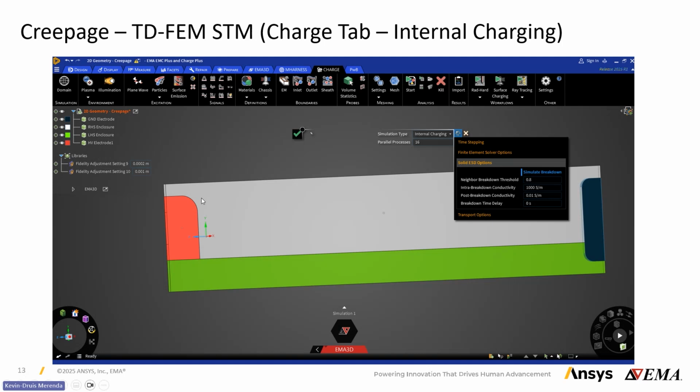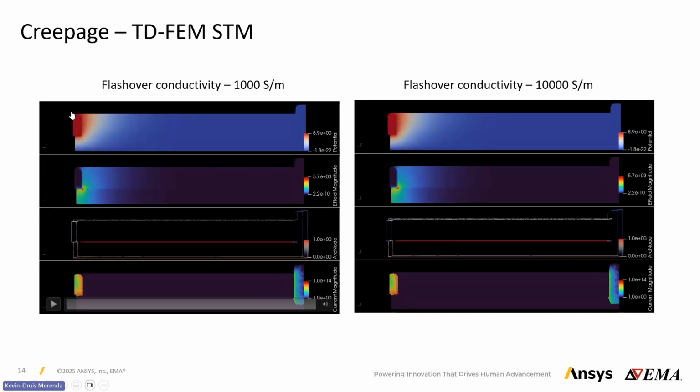In the release of 25R2, there is a new electromagnetic boundary condition, which is the E-field enhancement. And then you can actually create an enhancement factor along a surface of choice, which will then facilitate the discharge process in a given direction. And so here, this is very useful for a flashover simulation.